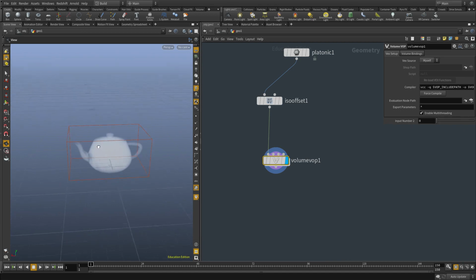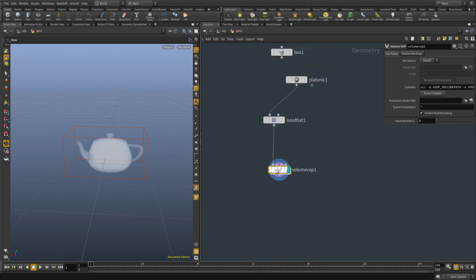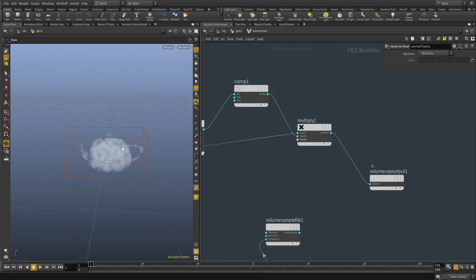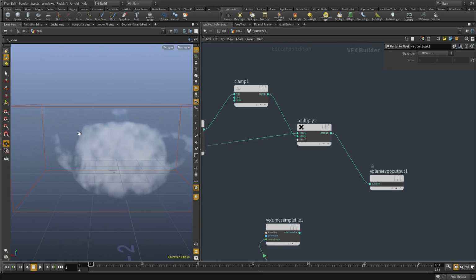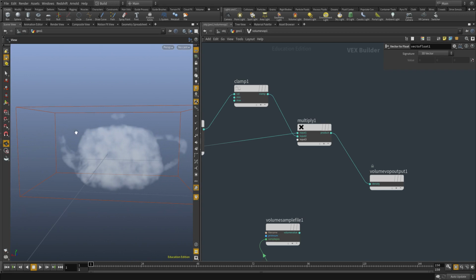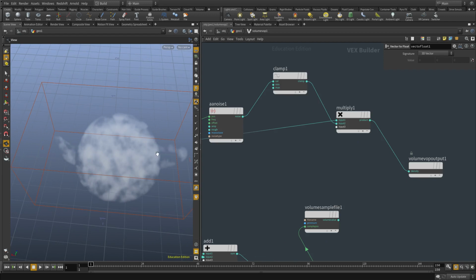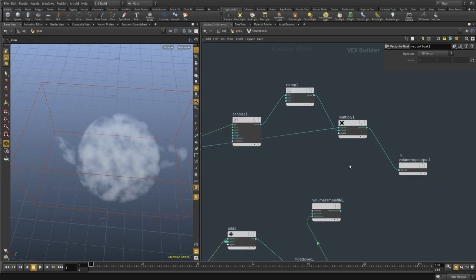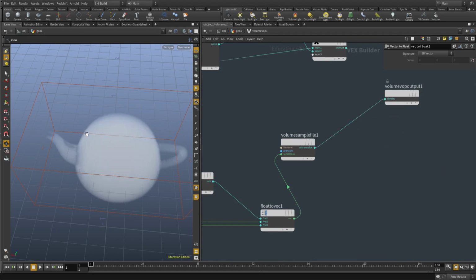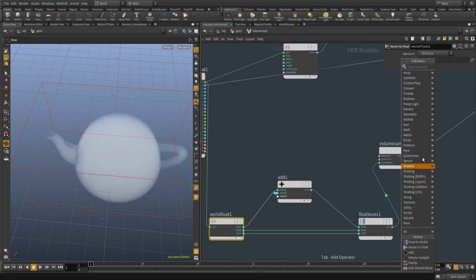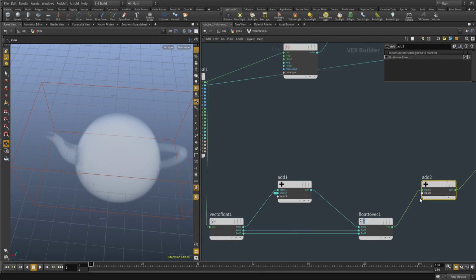We're changing where each of these voxels is sampling its position from, and we're adding this offset here. If you remember when I did the noise here, the noise is not breaking these edges, and the reason for that is because we're not telling any voxel to sample from a different location. Each voxel is taking its value from its current voxel position, and we're just multiplying the values by a different amount.